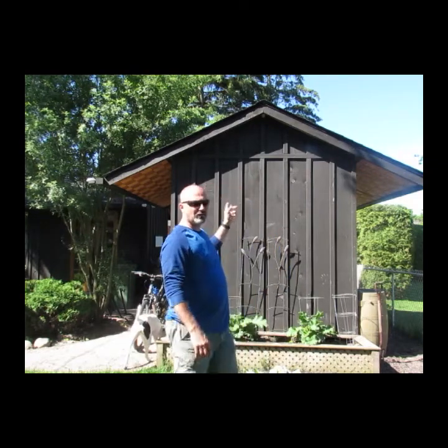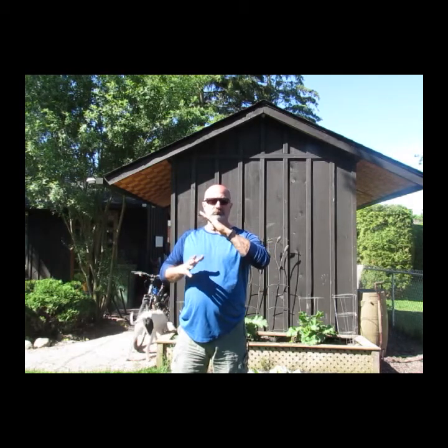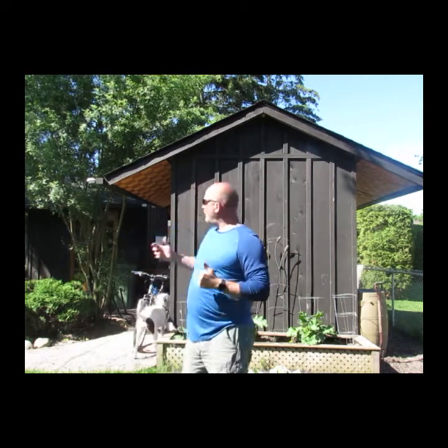What I've got here is approximately a 30-degree pitch. What that translates to is about a 7/12 pitch, is how they'll explain it. So for every 7 inches up, I go over 12 inches. That's the way my pitch is on this roof. Now, let's take a look inside at what I've done.